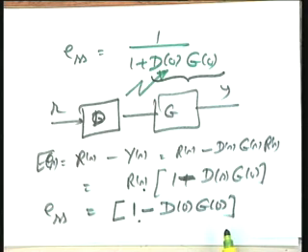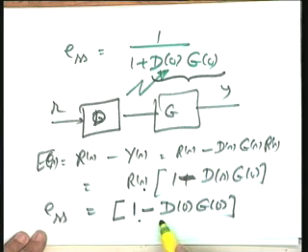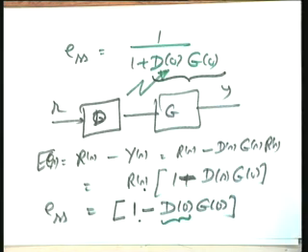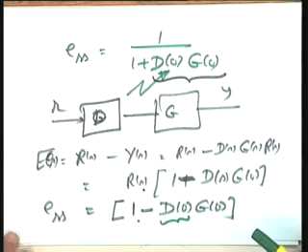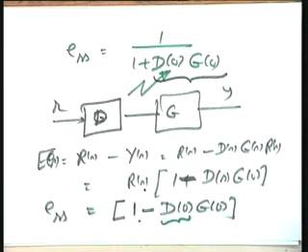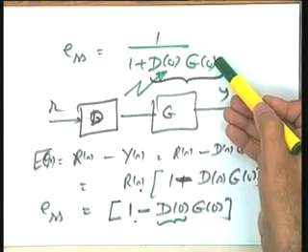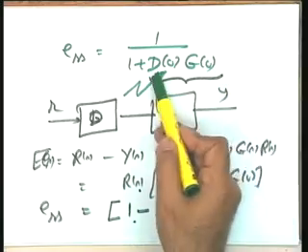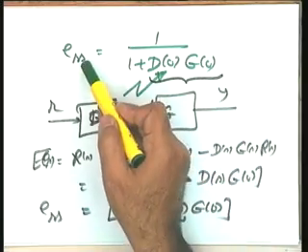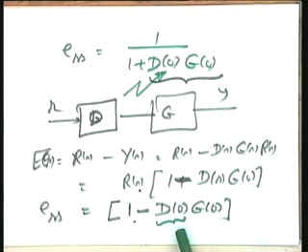In this particular case you see that you can reduce the steady state error to 0 by suitably designing D0. You make your D0 G0 equal to 1. So again please see, probably the steady state accuracy requirements can be better met with open loop control than with feedback, if there were no problems as far as robustness and disturbance rejection requirements are concerned. In the feedback case, you cannot reduce the steady state error to 0 unless you make D0 G0 infinite.